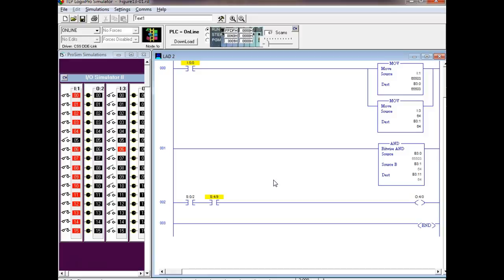Now, Siemens 7, the Step 7 software we got, when you start your program up, if y'all remember, I know that was a long time back, you specify which programming language you want to program. The one we used was Ladder, but they have, I think, STL and another one that's available for programming. So PLCs usually give you a couple of ways to program, and that depends on the programmer. You'll find out a lot of programmers like the more difficult language for people to learn. If they know it, that's the one they're going to program.